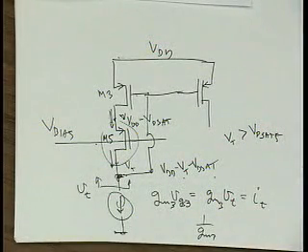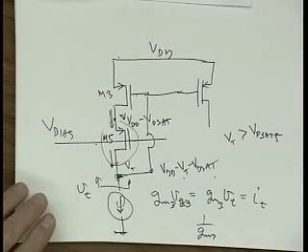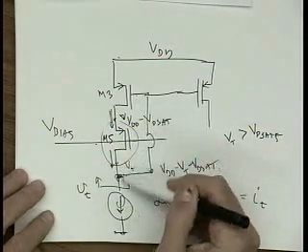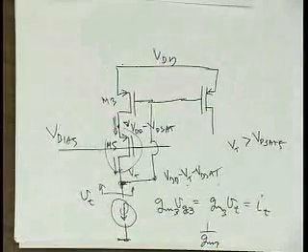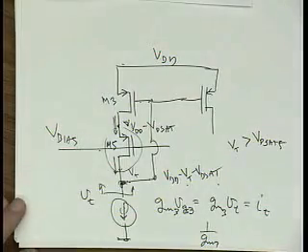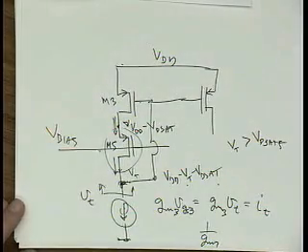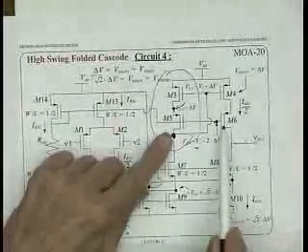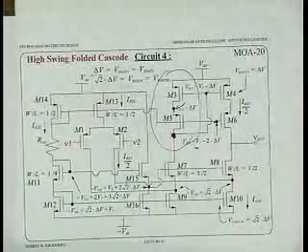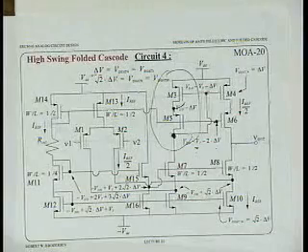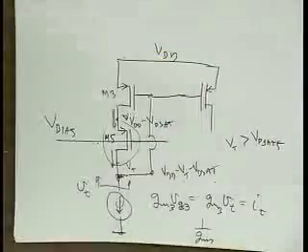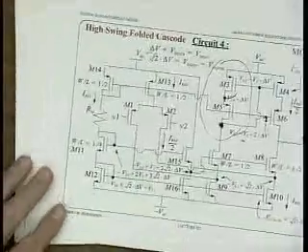Okay? And it's better than diode connecting two of these together, right? Because then we'd have two VTs plus two VDSATs. So, yeah. M5 doesn't do anything except add the cascode. You need it to be the cascode. Yes. On this side, it doesn't do anything. What it's for is on the other side, and it needs to balance the two circuits. Okay. All right. Really useful circuit.